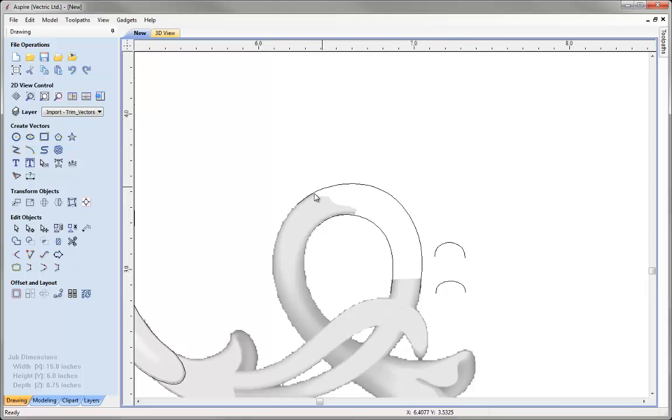Now for the first one I went from this vector to this vector, so that'll be my first rail, this will be my second rail. But then on the second one I went from this rail, which is the second rail, to this one. So I'm actually going to take that and I'm just going to hit H on the keyboard to mirror that horizontally. Now that almost makes no difference in this case, but it's just important to realise that I should have gone from the outside in if I wanted when I created that second one. Won't make much difference with the result we get here.